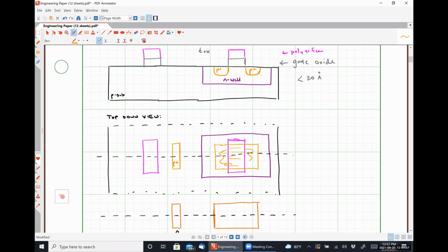This other way around, where we put the polysilicon down first and then use that as a physical mask, makes sure that can never happen, because we bombard that entire region. So there's literally no way the gate is misaligned to the source and the drain regions, okay?